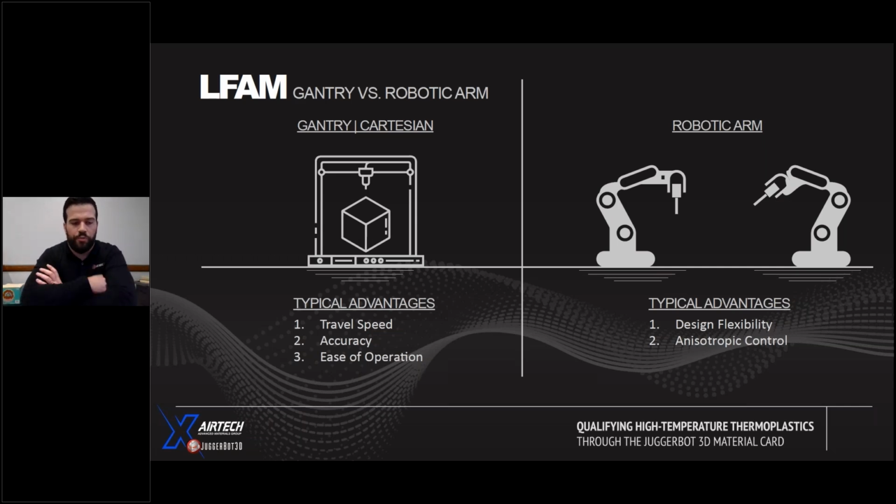There are obviously some things about 3D printing that are specific that we've seen, and we are admittedly biased because we're building systems with gantry-based extruders. I'm sorry, gantry-based systems. Typically, I think it's accepted that if you leverage those first three things that we just talked about, the build volume, the extruder specs, and the chamber construction, those will help to have a more comparable view of gantry or robotic systems. But it seems like there's at least a purpose for each version.